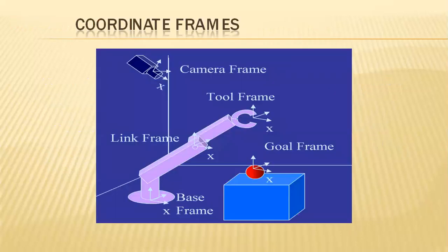See the coordinate frames, how the changes will be taking place. There is the camera frame, where the working environment of the entire pick and place robot action will be captured. Comparing the global coordinate system with the base fixing alignment is link 1, which has a pivot joint with link 2.